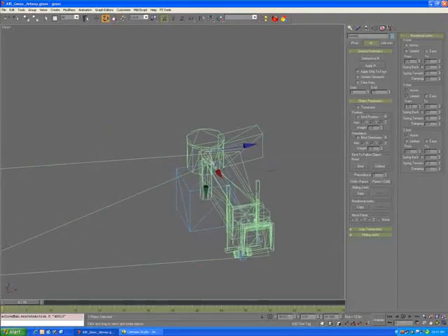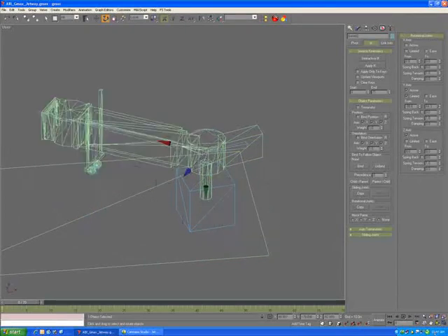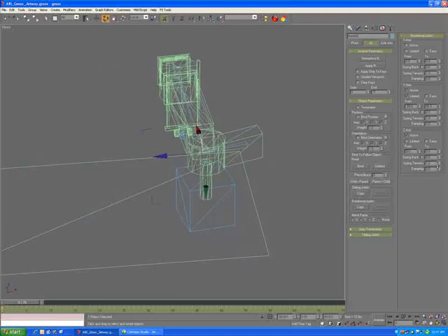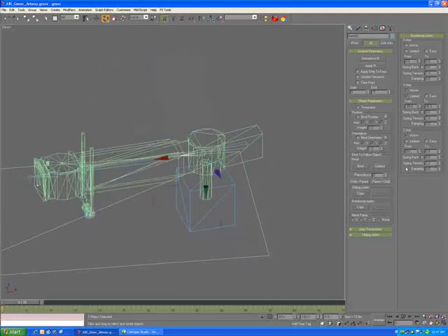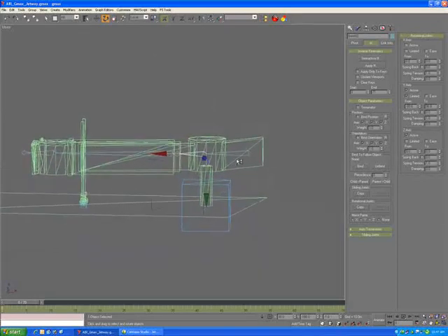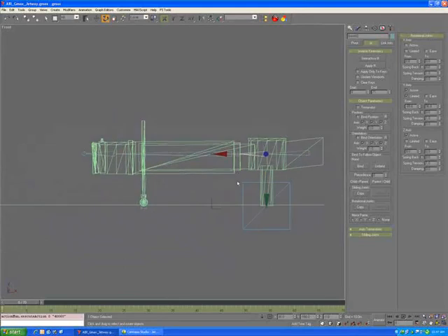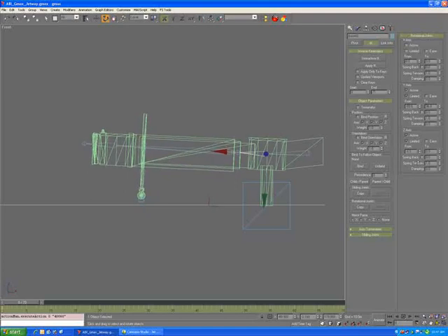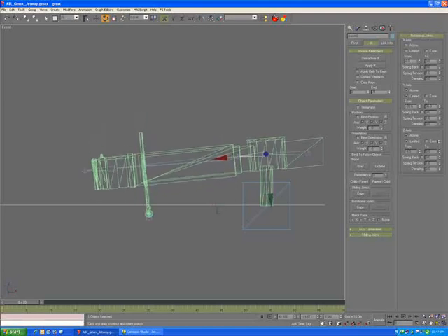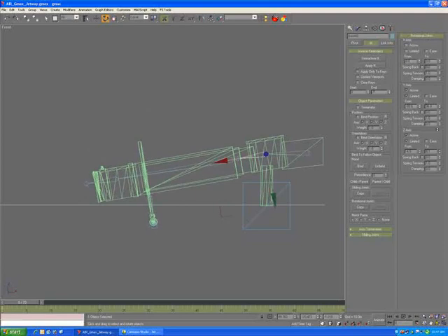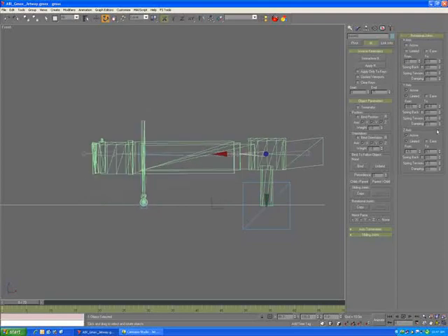So we'll go back about that far, and then we'll go forward about that far. And now we have the limitations. When solving for the IK, it will never exceed those angles. Additionally, we want to get the angles for the up and down movement. And so the z-axis, we're going to really quickly do some limitations, so it should probably never get any lower than that. So there, now we have the z-axis limitation. So we have x-axis, y, and z.